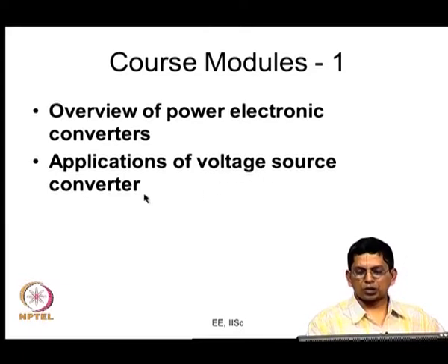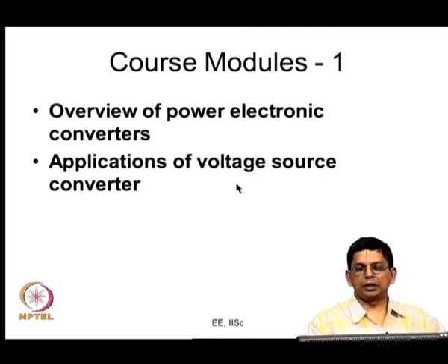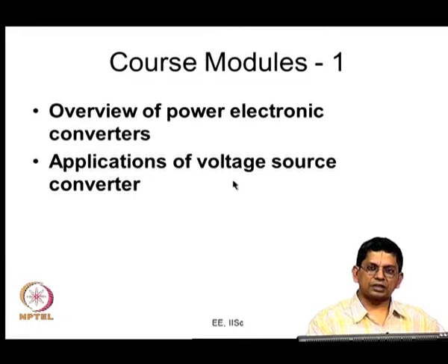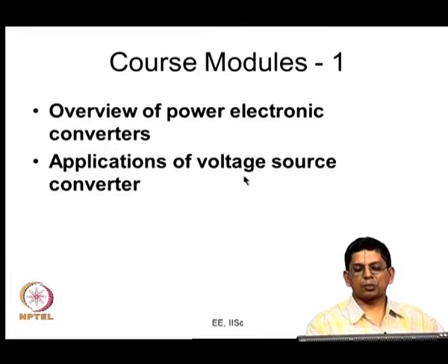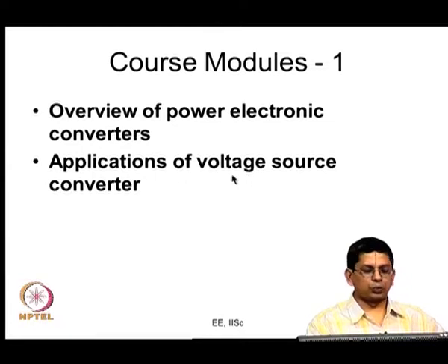You also use voltage source converters for active PWM rectification. You try to rectify at unity power factor, ensuring that the rectifier input currents are almost sinusoidal. We will have sinusoidal plus maybe high frequency ripple. So, that PWM rectification is another application of this, and we also have things like static compensation, and many grid connected applications are possible here. Here we briefly reviewed the applications, and we also looked at what kind of load models etc. could be used and so on and so forth.